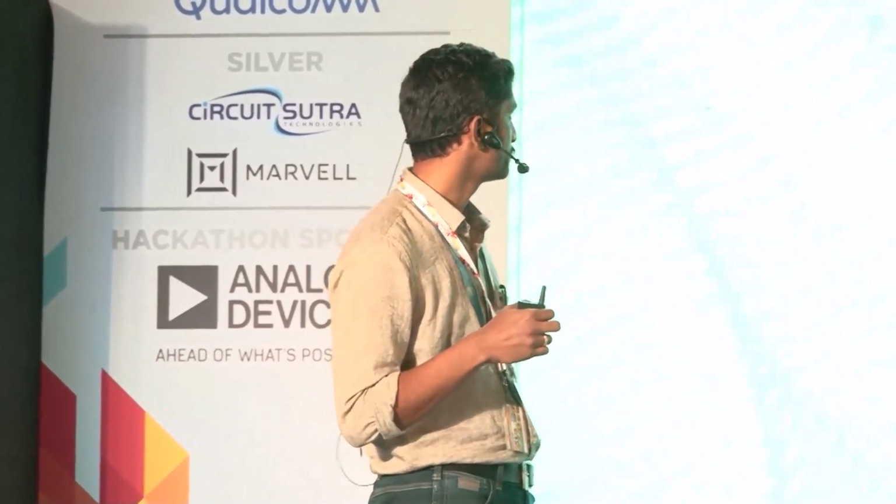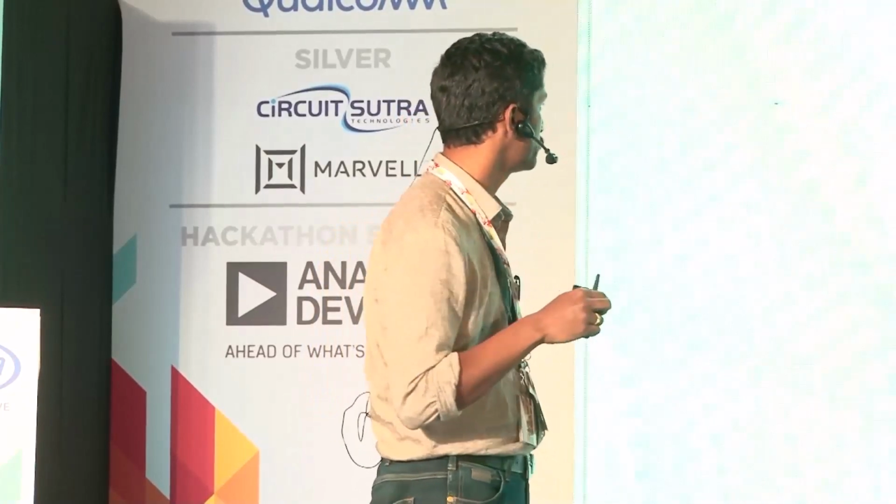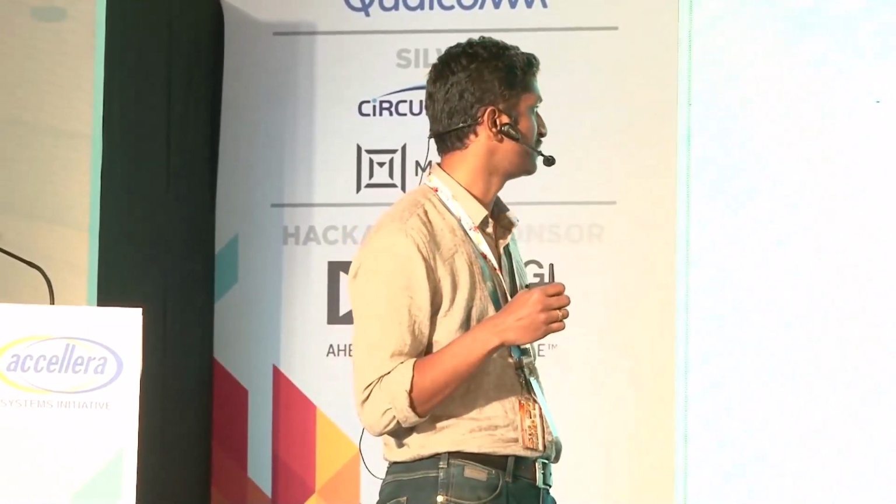Another usefulness of these formal checks was with whatever RTL fix we came up with. Since it was not caught with the dynamic simulations, it would have taken weeks to find a proper test case to create that scenario and test it. So we did the fix and tested that fix in a matter of days, which otherwise would have taken weeks.